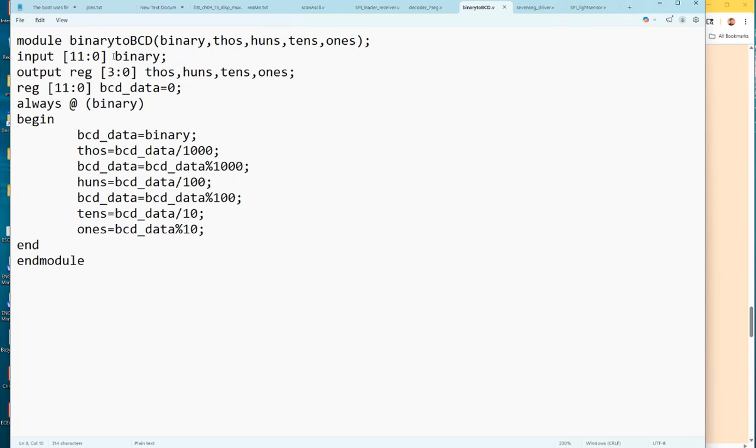So no matter what this data is, based on the 8-bit ADC's resolution, this step is really unnecessary because you don't have anything at the 1,000th position of the number. It doesn't have it. The maximum number you can get is actually 255. You're not getting anything larger than that.